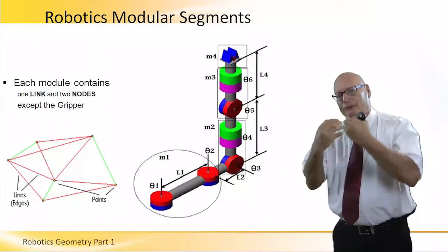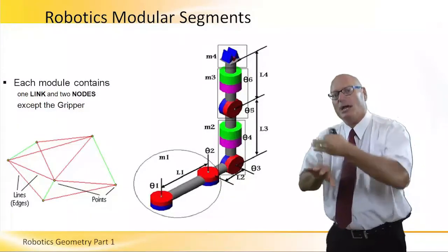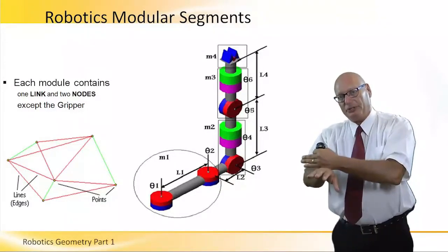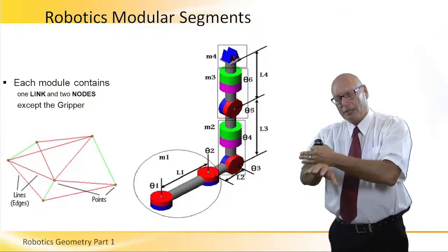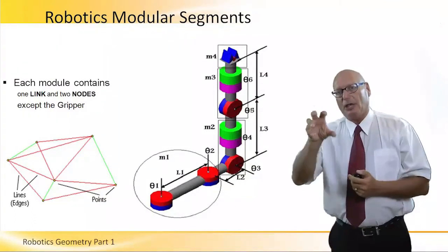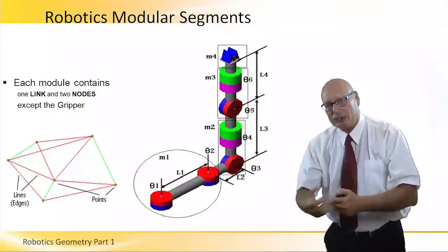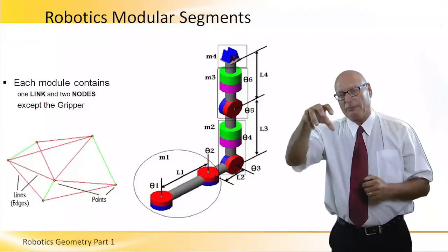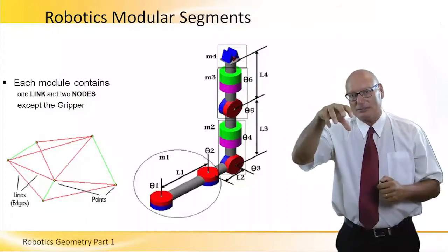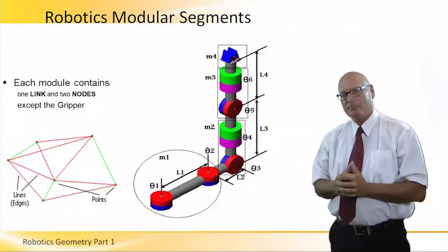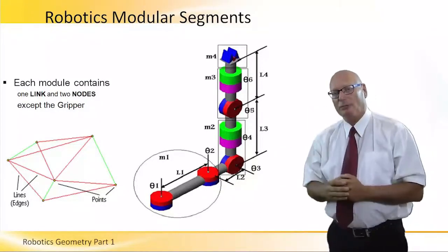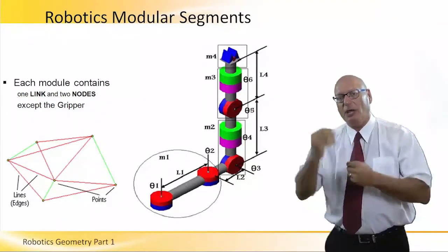Not only that, without an object the center of gravity is outside the holding point from a mechanical point of view, but when we add the weight and torque, acceleration and deceleration, and inertia of the object that the gripper moves, we even increase the problem of having a center of gravity away from it.